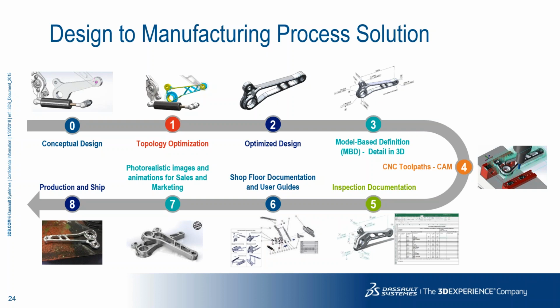provides topology optimization. So the ability to say, hey, here are all my constraints, let SolidWorks Simulation automatically figure out what is the best shape of my model. What is the geometry? What should it look like? So that I meet the constraints and also meet the manufacturing requirements. Is it going to be molded? Is it going to be cast? Is it going to be machined? I can put these parameters in and actually SolidWorks will feed back what that shape should look like.